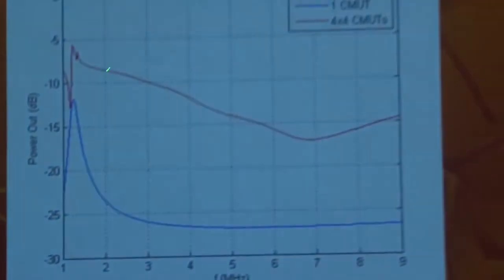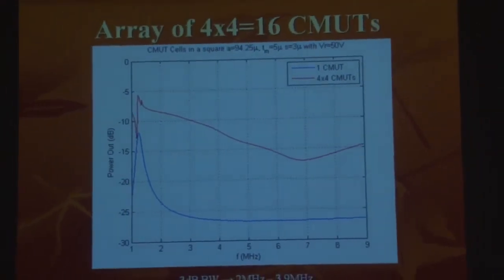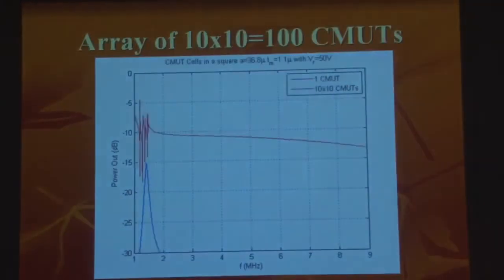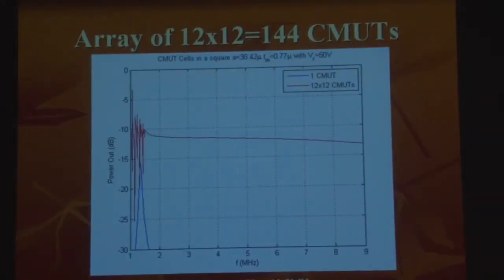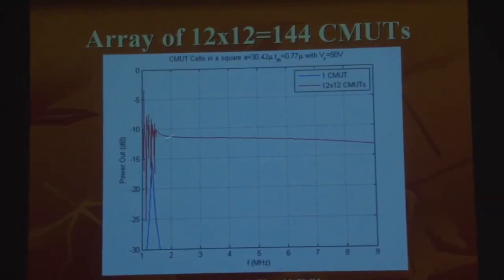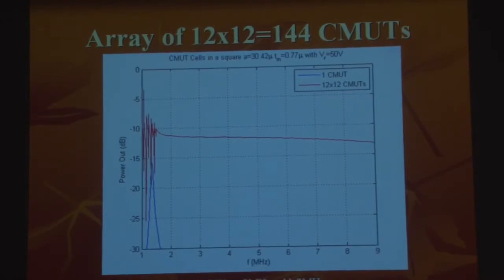Do you have any preliminary design configurations that you see as optimal? Well, just like the ones I showed. For example, suppose we design this to work at 2 megahertz. We deliver here, let's say, minus 8 dB. A conventional design is somewhat similar to this, and you will get minus 12 dB. So we're talking about 4 dB additional power with the same excitation voltage.